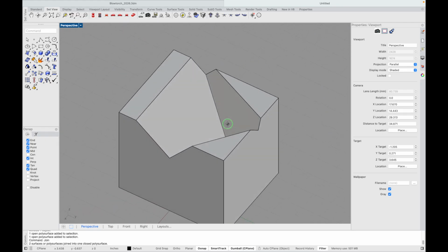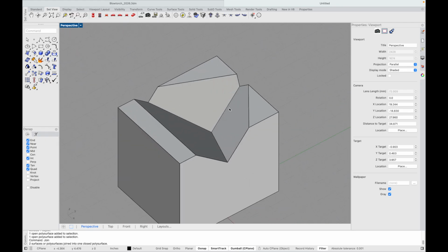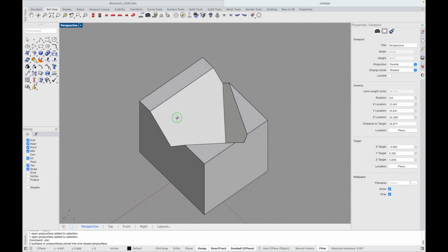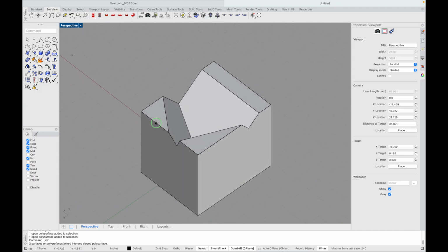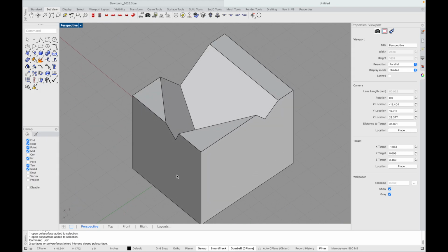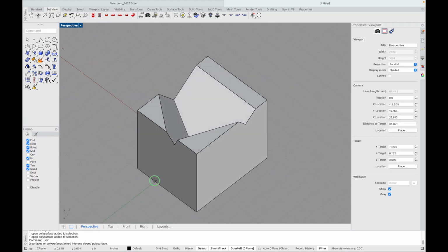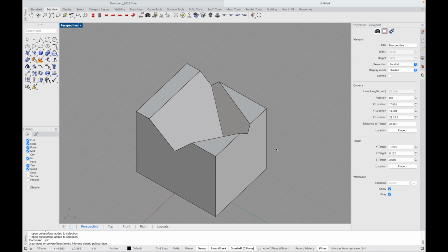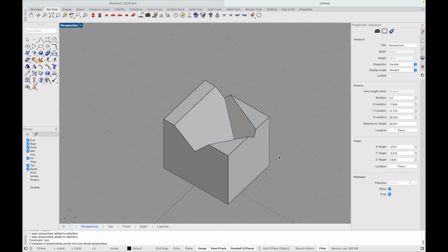So it's a really hard shape to make if you try to make this on its own, but if you need to subtract one geometry from another one, then that's how you can do it. Now, what I just did was essentially a Boolean difference command, but step by step. So again, if your Booleans are failing, just do that, and that should hopefully make it work.